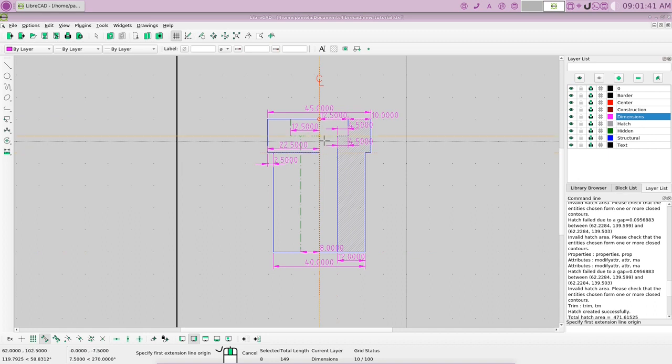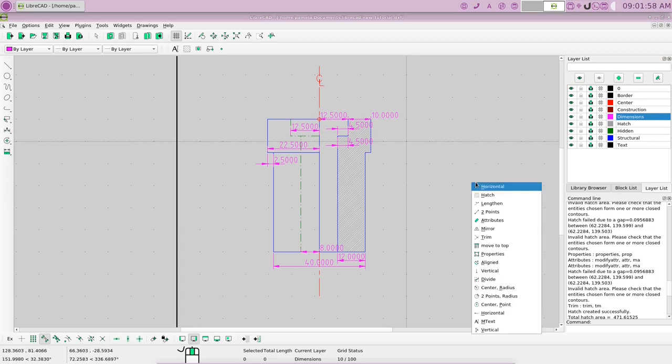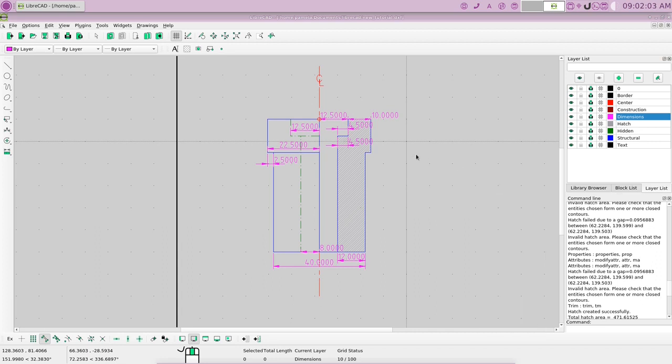What we might do is, you see this here is a little close for comfort, so let's get rid of our dimension tool. Let's click on that one and hit the delete key to get rid of it. I want to move it a bit. Let's right mouse click, choose your horizontal dimensions again, snap on end, snap there, and come up.